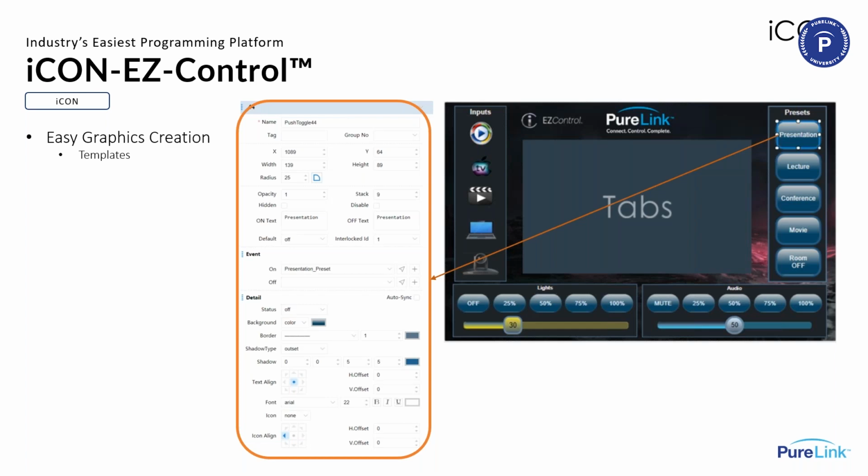What I'm presenting here is saying that every component that goes on your touchscreen, you have numerous parameters that you can adjust so things look and feel the way that you want them. So I can change button sizes, the color, the font. I can have different text, whether the button's in the on or off state, I can have it a different color if it's in the on or off state. And I can also have them either a solid color or a gradient color in one state and an image in another, or both, or vice versa. So again, anything you want to do is possible here.